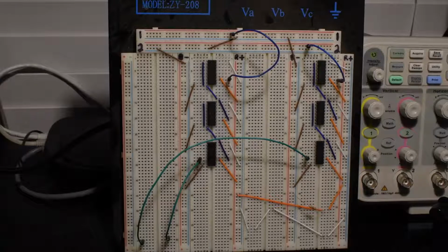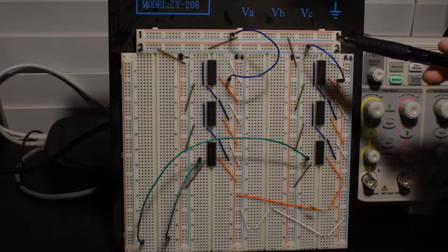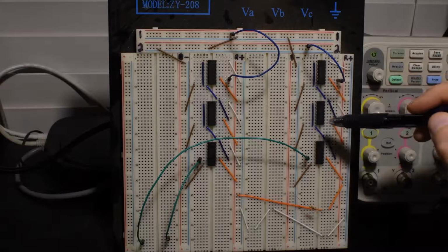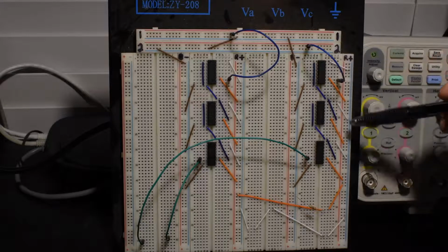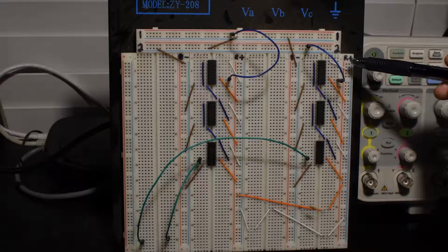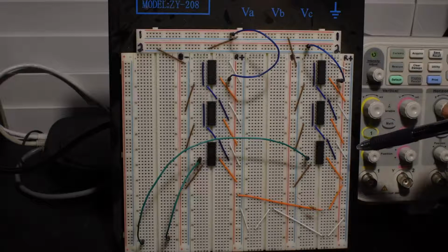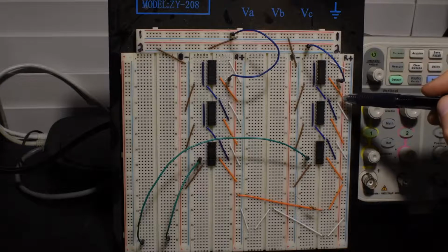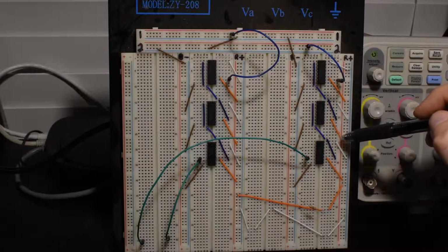So this is what we're going to use to measure these really small frequency differences. This is basically just a bunch of 12-bit binary counters organized into two chains, one for each of the oscillators that we want to compare. So we've got a color coding system here where blue is the clocks, the two clocks for the two chains. Brown wires represent ground. The white wires represent the plus power voltage, so that's going to be plus 3.3 volts in this case. And then these each have a reset pin also, so these orange wires represent reset.